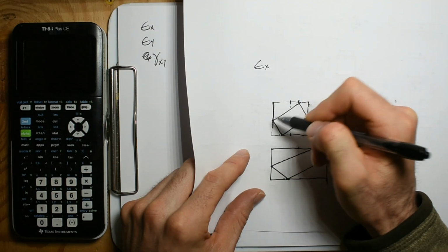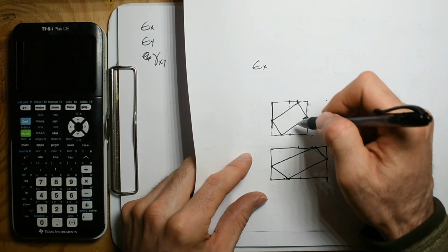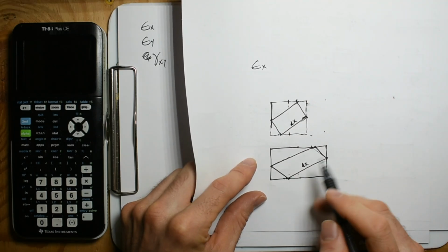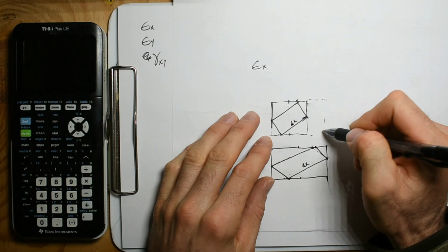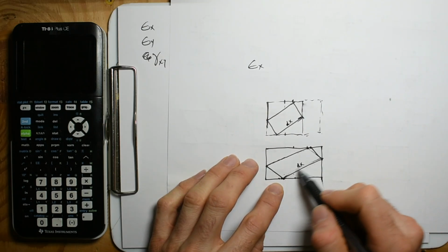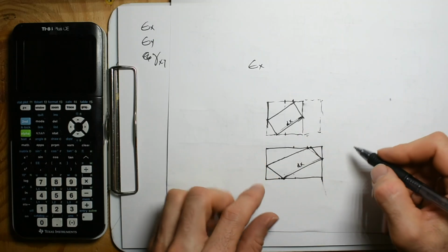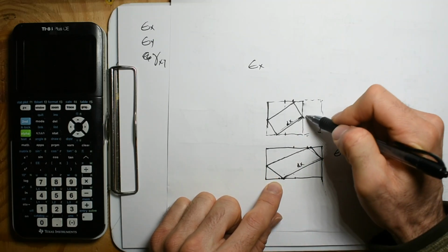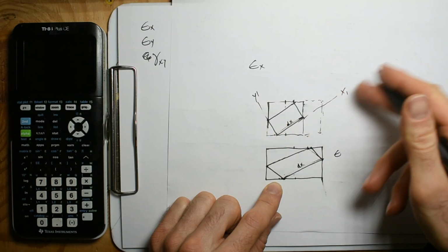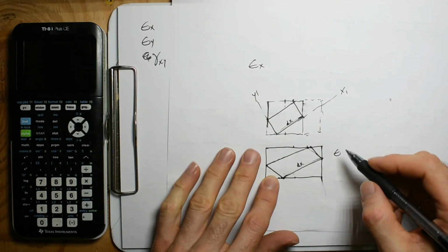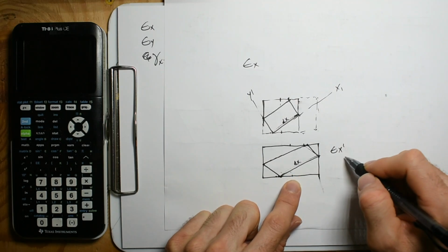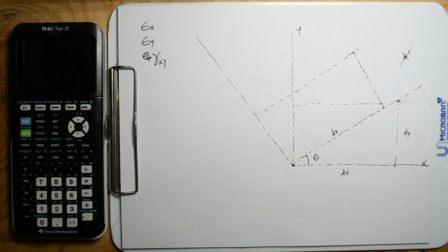So what we had was, hey, this was our dx, and now we can analyze, because I know that I'm going to have this happening in the x. Hey, I can now measure this length using geometry compared to that length, and I can find the strain, and we're going to call this the x1 direction, y1, or x1, x prime, y prime, however you want to do that. But now I can know the strain in this x prime direction. All right, booyah.